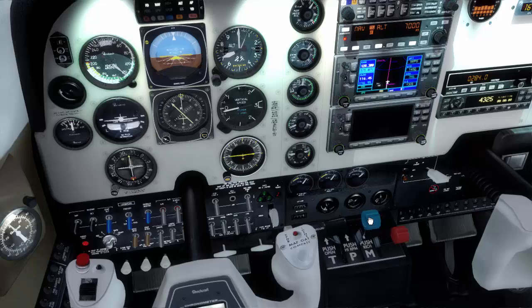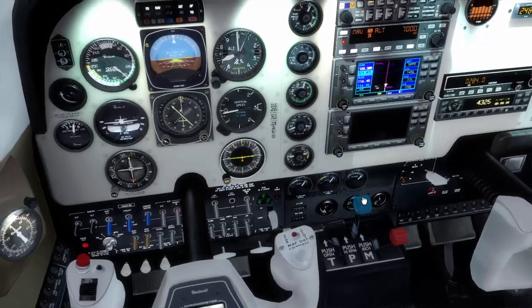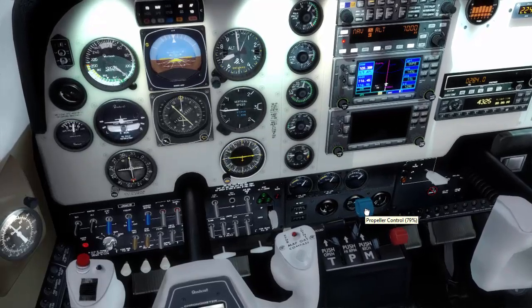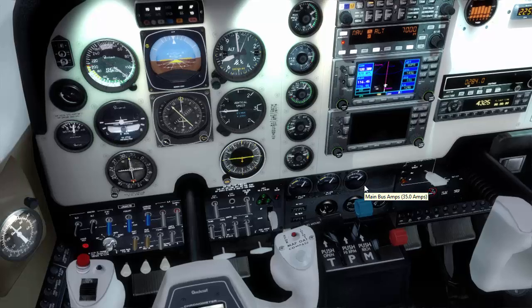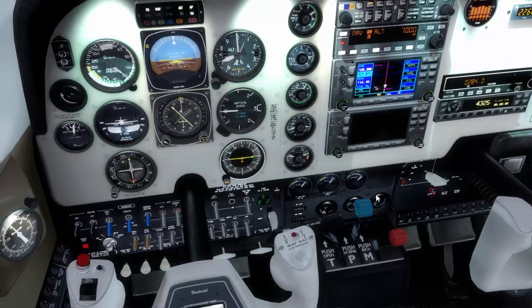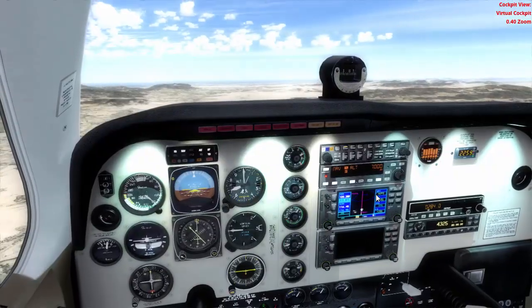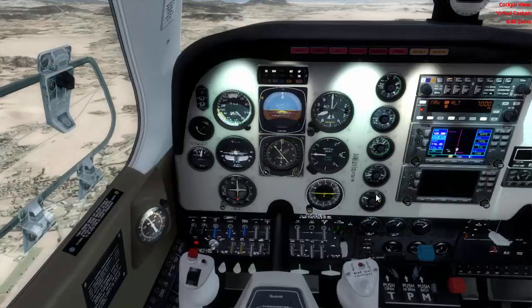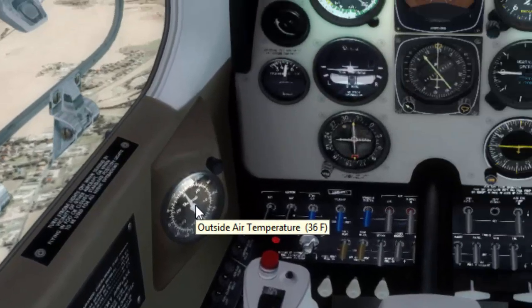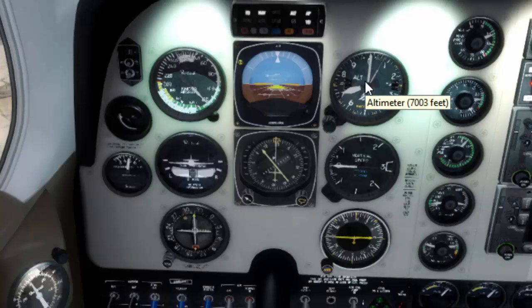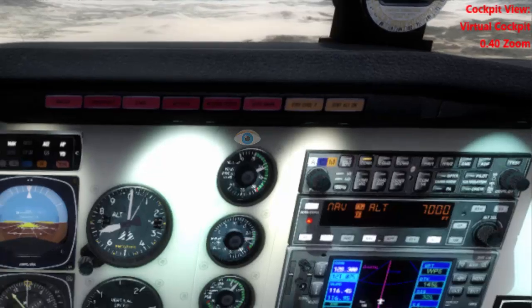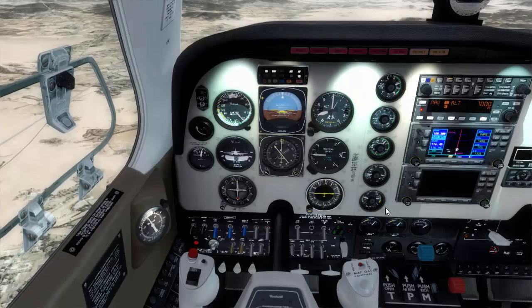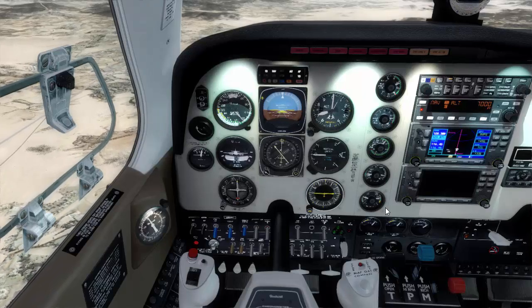Because we're reaching 7,000 feet right now, we will see the aircraft is not gliding anymore, and we are not using its own weight to glide anymore, and then the speed will decrease dangerously. So to avoid that, we will need to put power into our engine, and right now we will have to move forward the black lever, and the blue lever as well, okay. Remember always to monitor the exterior temperature at the altitude, because we will need that valuable information to use the cruise performance tables. And as you may see, again we have a value in the manifold pressure gauge, okay.